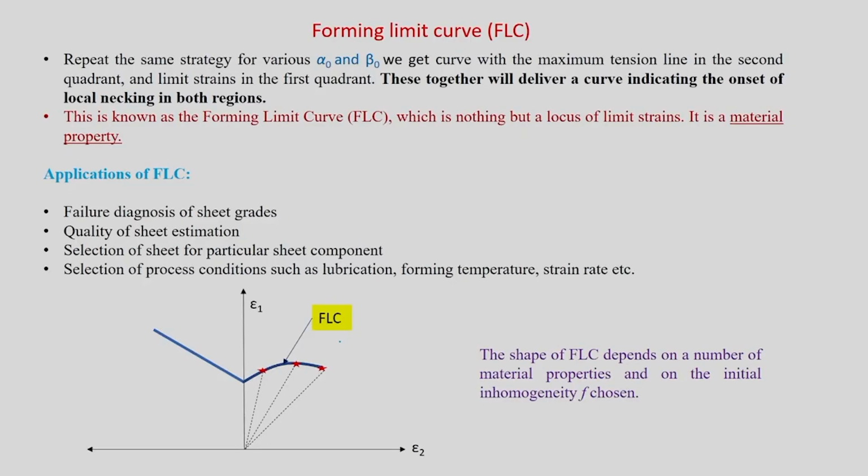Which means before going to the component level stage, you need to get the forming limit of that particular stainless steel, for example. Let us say SS, stainless steel, of some grade with a particular thickness of 2 mm. You need to have the forming limit curve for that. Standard methods can be used, and you have to evaluate. And in none of the locations in that actual component can the strain cross the forming limit curve. Okay, and you will see that in an actual component.